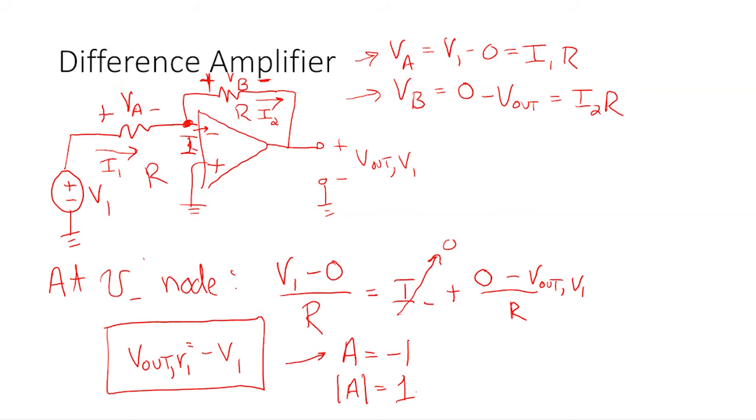But the reason I think we always do that is because no gain kind of implies 0 as the value, right? You're correct, Matthew, in that output and input are the same magnitude. So it's not getting bigger or smaller, right? That is kind of no gain. But I think the term no tends to imply to people that there's nothing there, right? So we use the term unity gain.